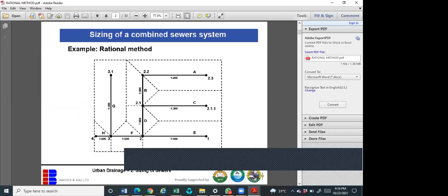So if we come to catchment B, the total area becomes catchment A plus catchment B, which is this big. When it comes to catchment D, the catchment that is being supplied water, the catchment that water is flowing into becomes this. Are we together? So this one flows into this one, C flows into D, E flows into F, G flows into H.